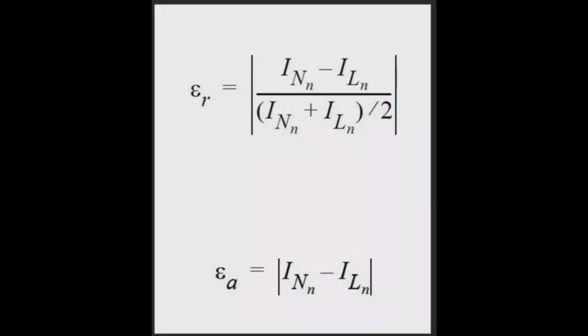And it doesn't work because in a microwave circuit, we have a combination of very large components, like the output of a power amplifier, and we have very small components, like intermodulation products. Well, if you just took the norm, you would have a situation where you think that everything is converged when the smallest components are not, because remember, the larger components in that case are going to dominate the convergence process. So you have to have some method that takes into account both the large components and the smaller components, and that turns out to require quite a bit of thought.